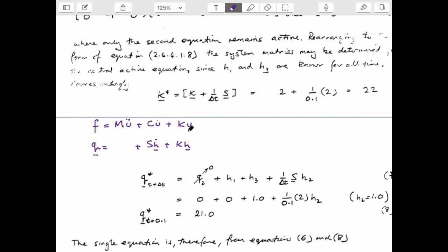We operate on the nodal values of heads, displacements. We operate on the nodal values of rates of change of those parameters. This is called damping rather than capacitance. And in structural mechanics, we have a mass matrix and an acceleration term, rate of change of velocity, so this is dv/dt. And of course this is Newton's second law, right? F equals ma. And so that's where that comes from.